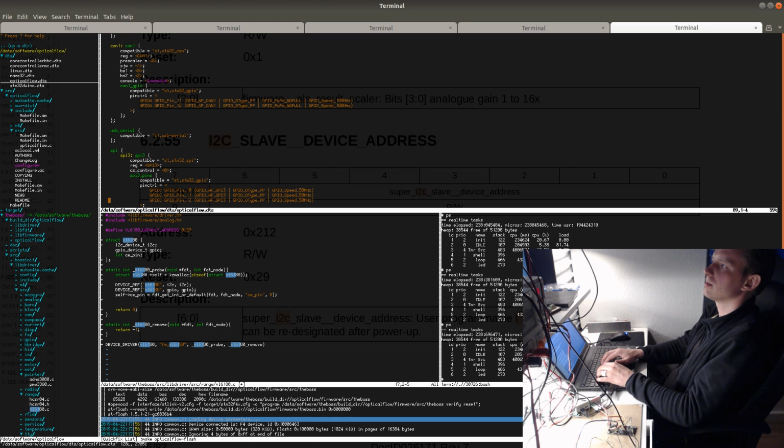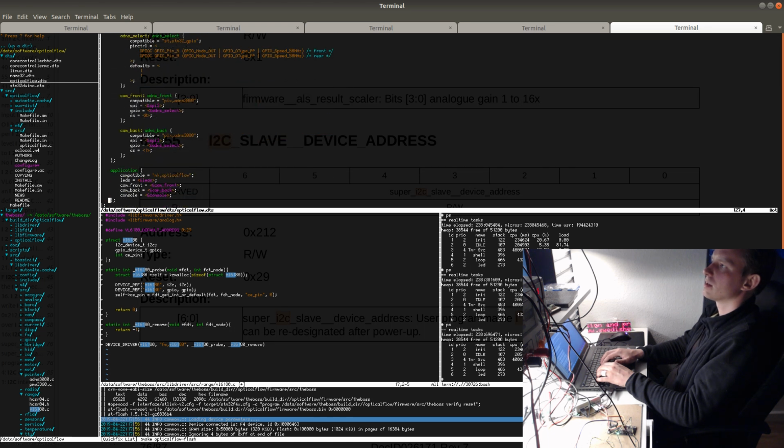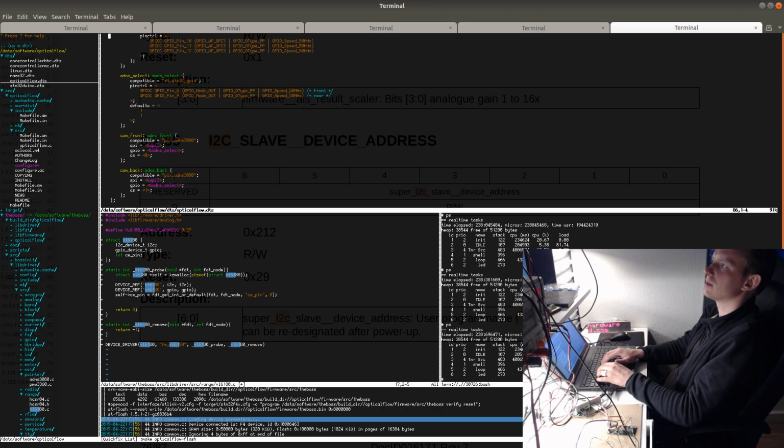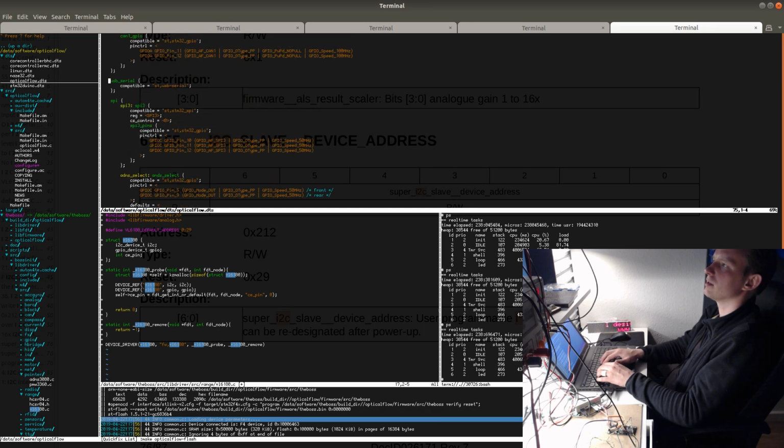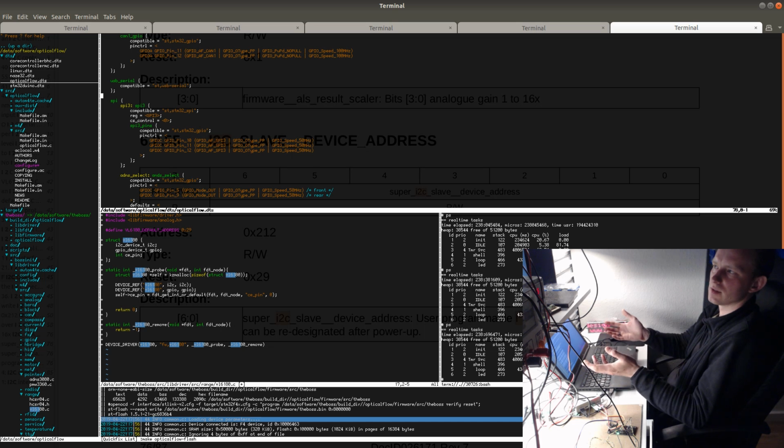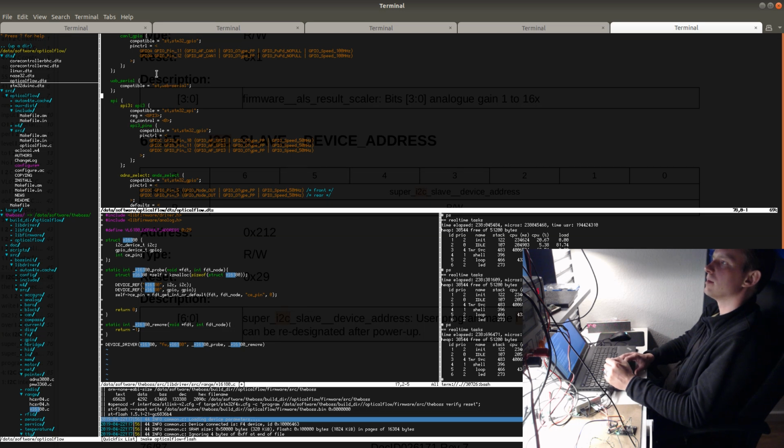One of the important things here to think about is that I have to place the initialization of the GPIO pins before I initialize any of the devices, because if two of the devices are going to be enabled at the same time, for example, if the chip enable pin would end up being default high, which by the way it ends up being, then I won't be able to talk to any of these chips. So I have to do it like this. Let's add it here.